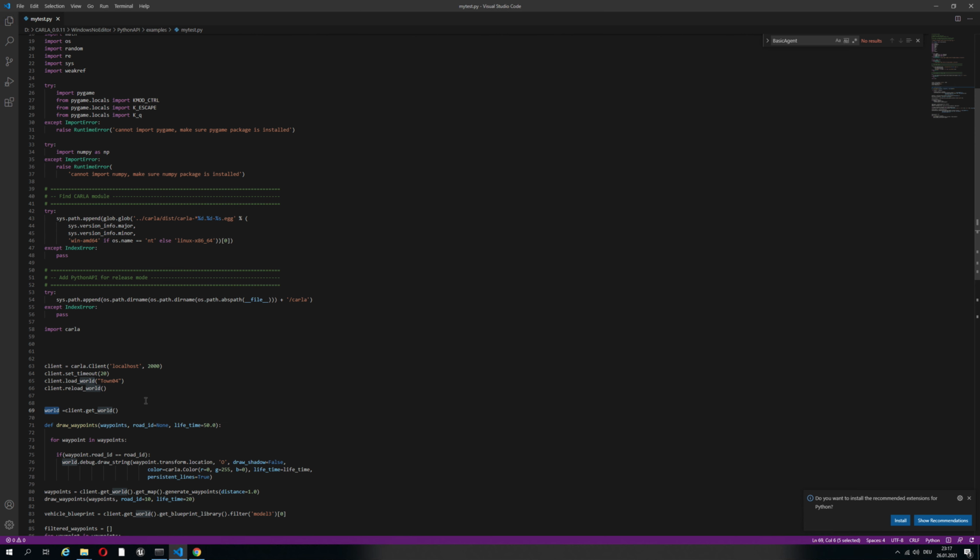So let's say you have the coordinates of the lane on the right and the coordinates of the lane on the left, then you average the coefficients. Let's say the lane on the right is a polynomial curve and the lane on the left is a polynomial curve, and these curves have coefficients. If you average these coefficients, you would get the model of the curve in the middle, that is mainly facing the car. And this curve you can use as a reference for your controller, so the car needs to follow that curve, as we have seen in the Unreal Game Engine simulations.